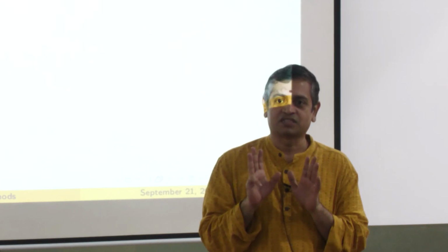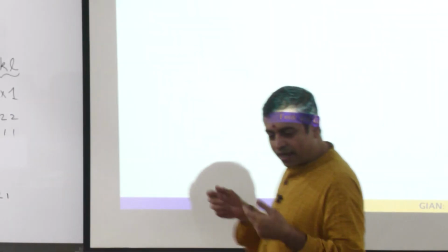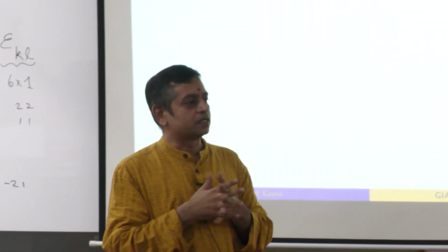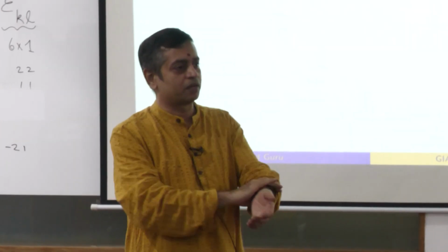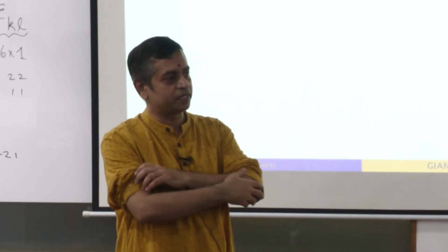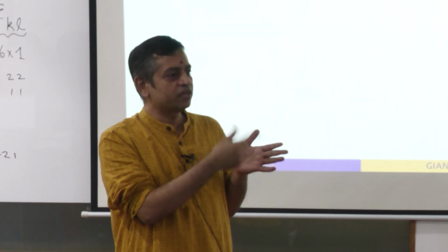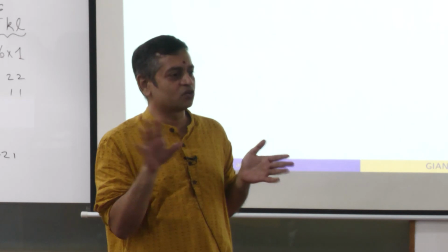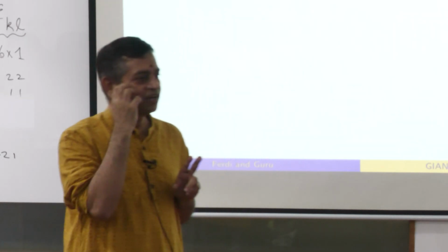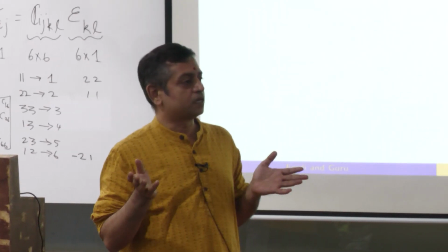Independent components, there are only 3 for a cubic one. Why are there 3 for cubic? The cubic anisotropy can be represented by one number, which is called the Zener anisotropy parameter. For isotropy there is a relationship between the 3, so one independent component goes away, and there are only 2 left. Those 2 can be any 2 moduli.